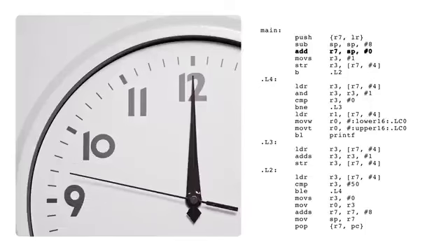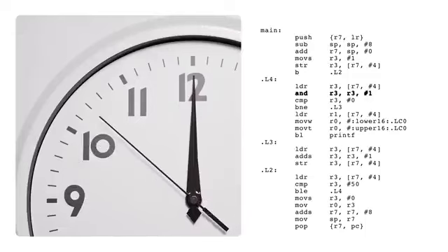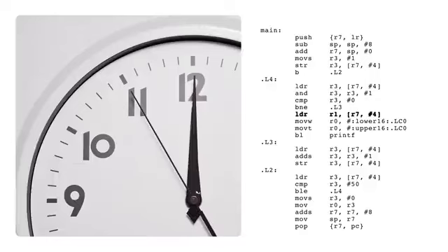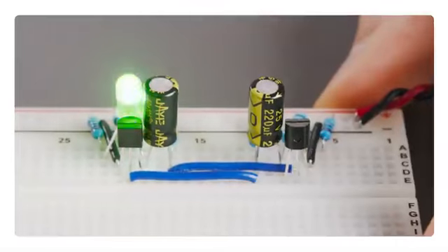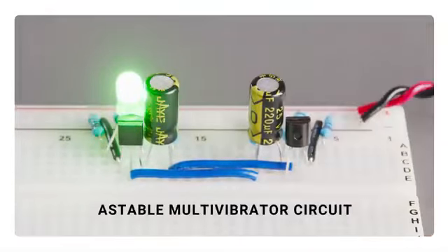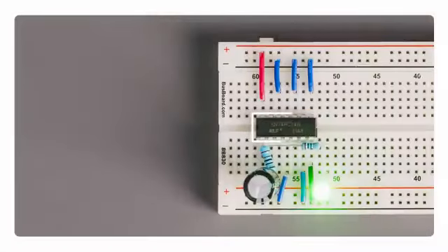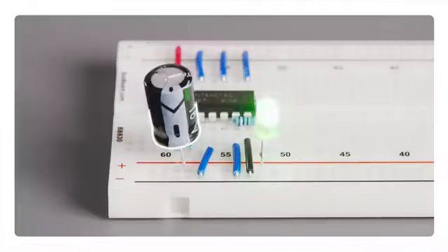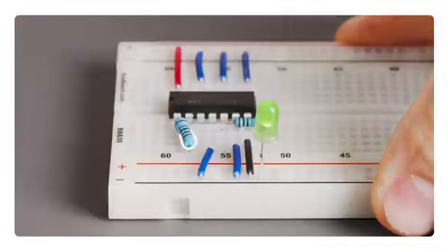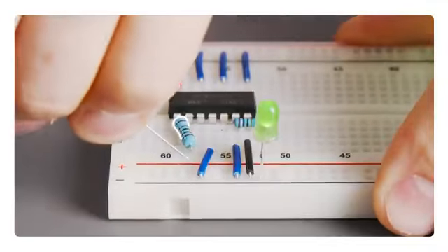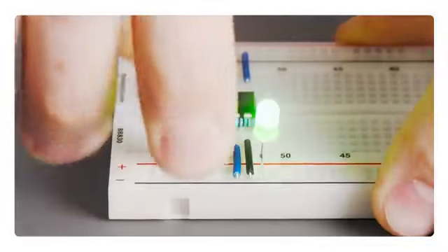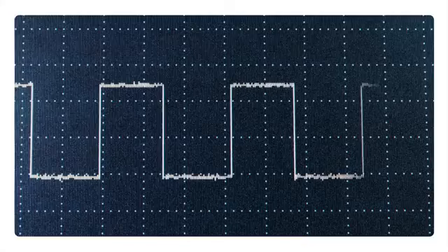So every time there's a clock tick, that tells the existing components that they need to perform an action. So you get a signal that says, okay, process the next bit, process the next bit, process the next byte. You can make a simple clock circuit out of transistors, capacitors, and resistors. This one's pretty slow. You can also use an integrated circuit designed for this application, and in both scenarios, the speed of the clock depends on this resistor and capacitor combination. So we can speed up this clock easily, and the signal looks like this.